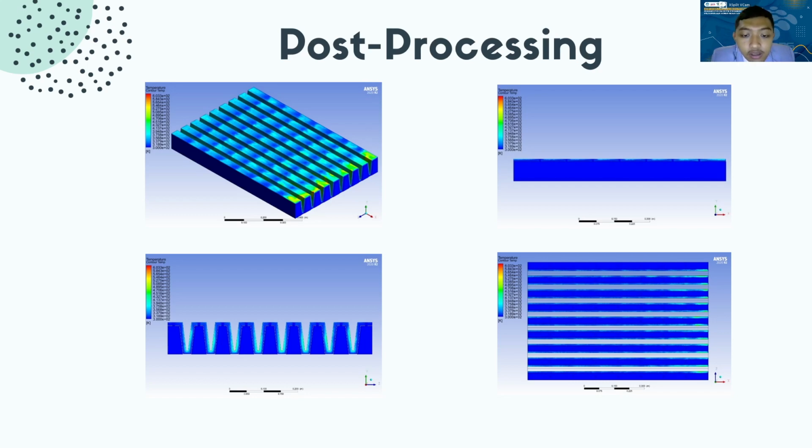603 Kelvin. The cause of the higher temperature in the space between the absorber plate and the jet plate when compared to the other areas is because there is still no interaction or meeting between the air inside and the air coming from the inlet side. The air temperature in the space between the absorber plate and the jet plate decreases when interacting with the inlet air flowing as cross flow through the jet impingement.